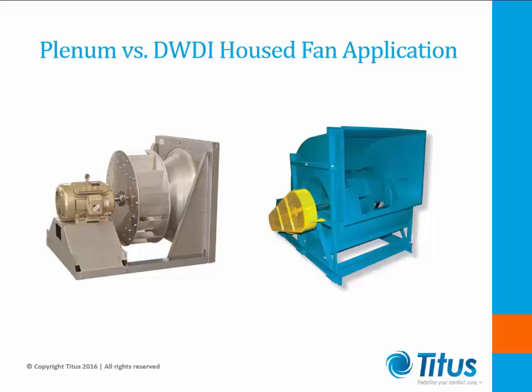Lastly, velocity profile. Due to the relatively small outlet blast area of a double-wide fan, an air diffuser must be applied to the discharge of the fan to obtain an acceptable velocity profile through the next component. Air diffusers add static pressure, which decreases fan efficiency and increases fan noise levels. Plenum fans positively pressurize the entire cabinet. They do not require a diffuser and its associated performance losses.